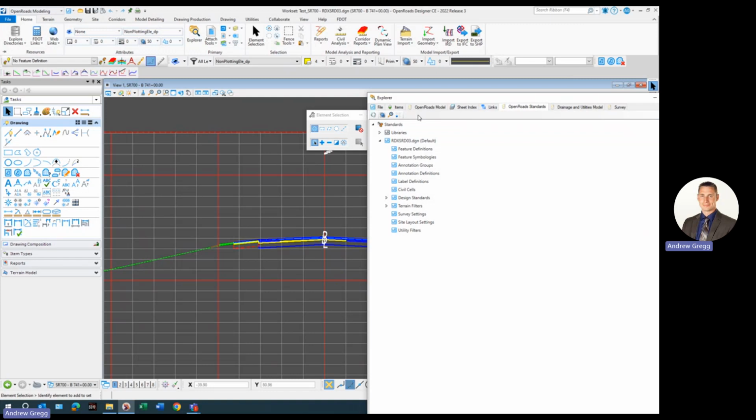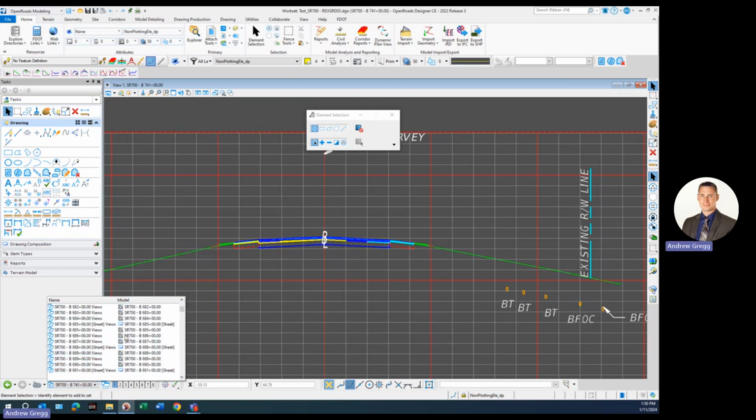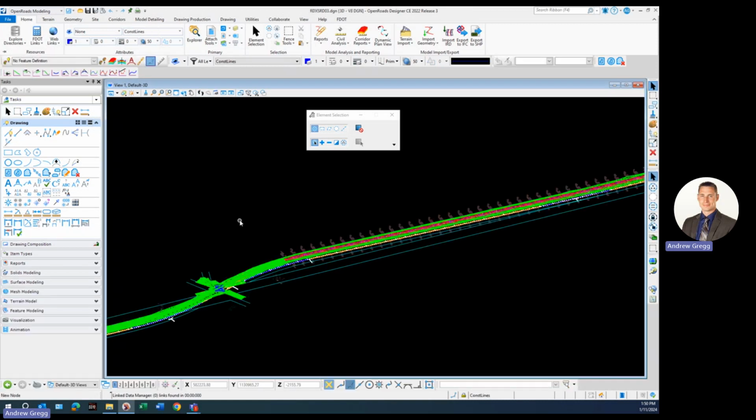To start out, we've got to make basically a whole new annotation group. I've talked with Mitch about creating separate, multiple groups, but that's a different discussion, so I'd get with him if you want to know more about that. You can see here under Open Road Standards, under the Explorer, there is no annotation group currently present. The reason I made this mistake, as a reminder for everyone, is that you need to be in at least the 3D model in order to get started.